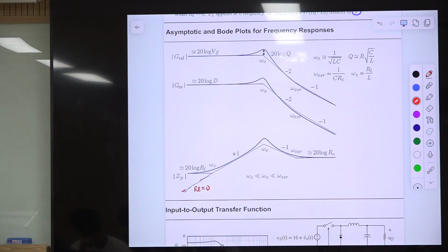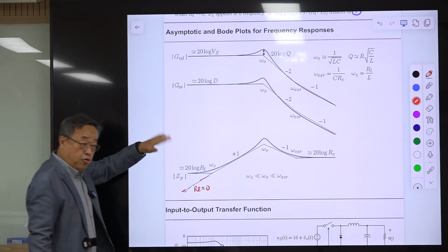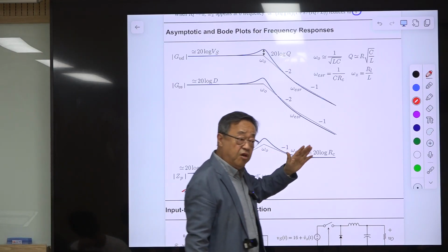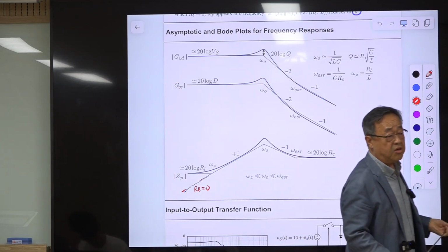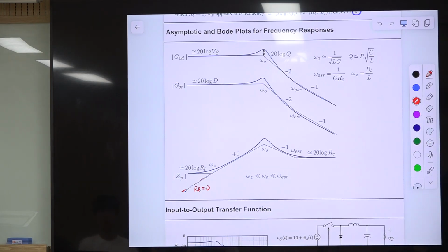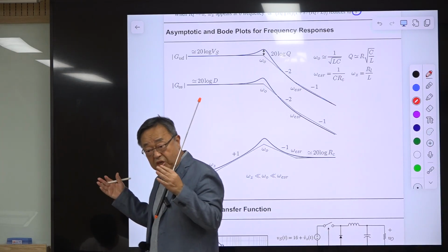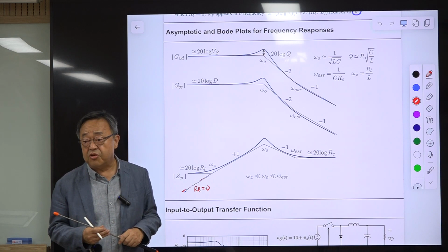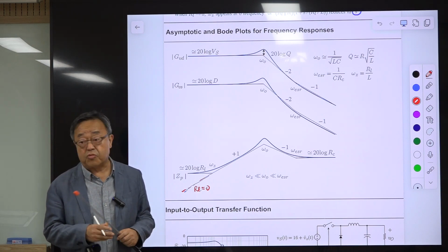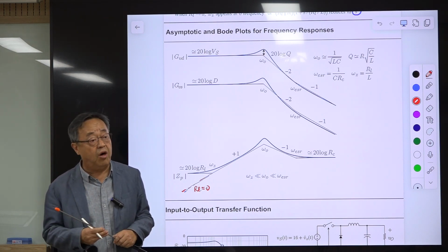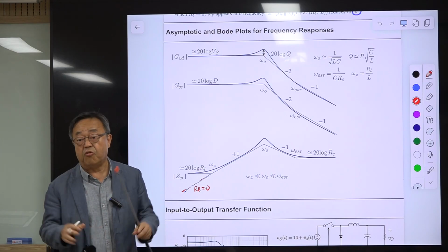And the implication of this: from these steps, we derive the small signal model of the power stage, and we derive the small signal model of the modulator block, the PWM gain. Later on we will derive the small signal model of the compensation circuit, which is extremely easy. That circuit is already linear. You know how to derive the gain of an inverting amplifier. So we have everything.